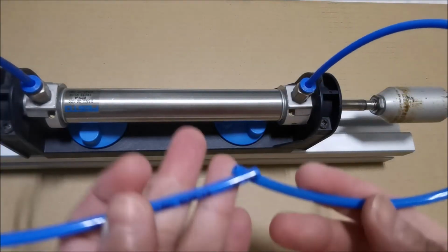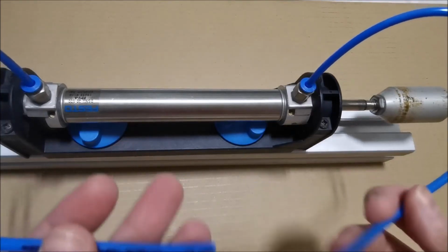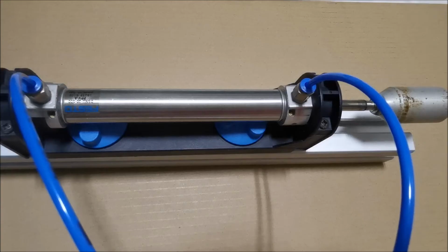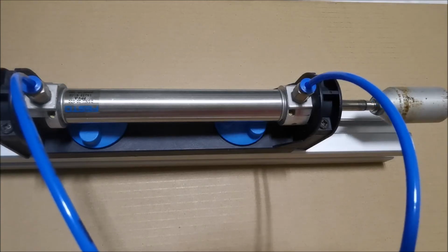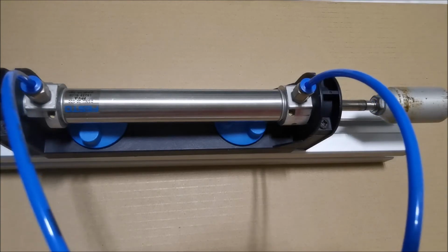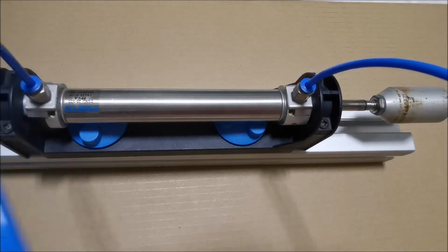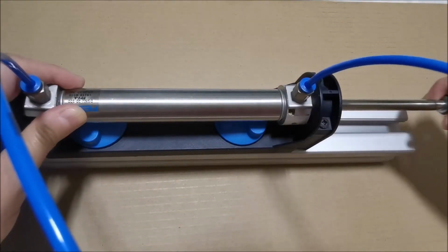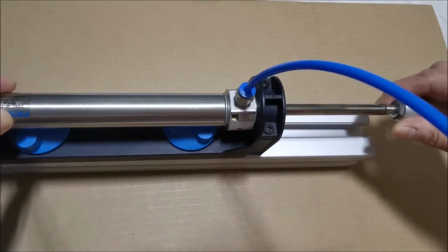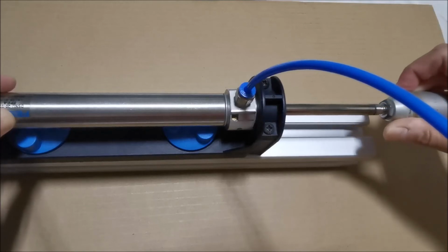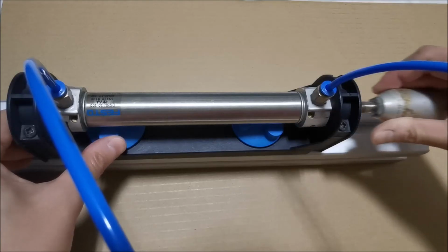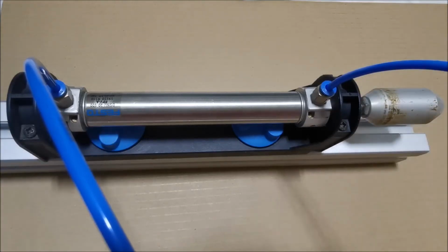Okay, so where are these tubings going to be connected to? Later on, you will know that they will be connected to the directional control valve, whereby your directional control valve will be connected to the air manifold, or we call it the air supply, so that when there's air coming in from the ball side, which is here, the cylinder will extend. You can actually see it extend. However, when there's air coming in from here, the rod side, you can see that the cylinder will retract.